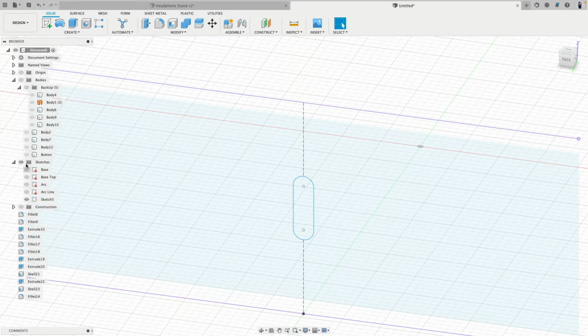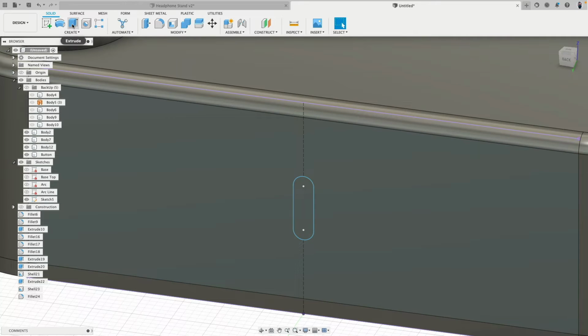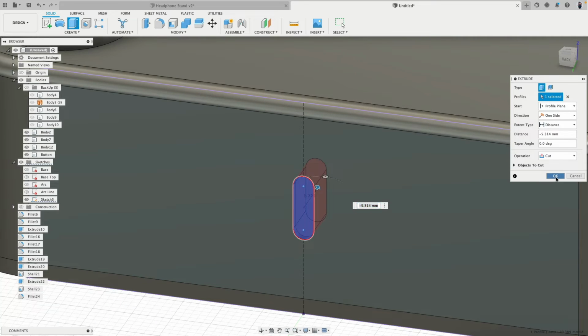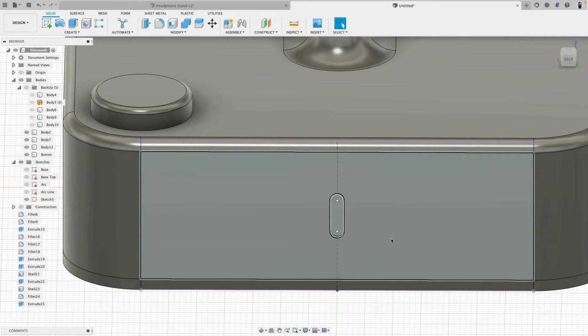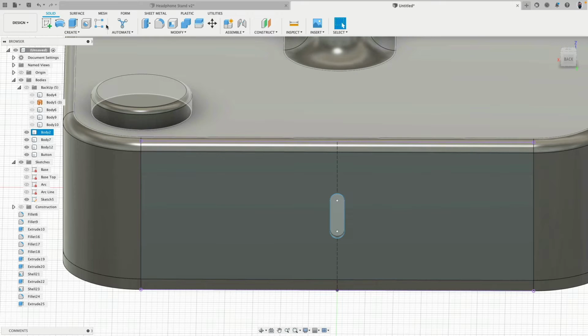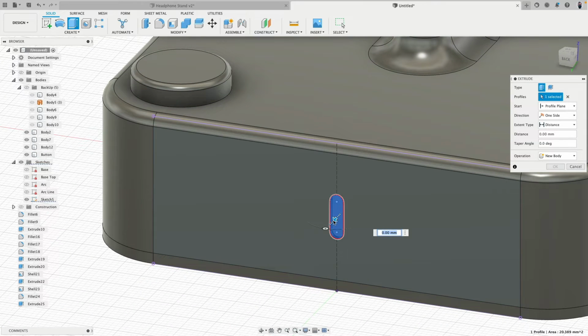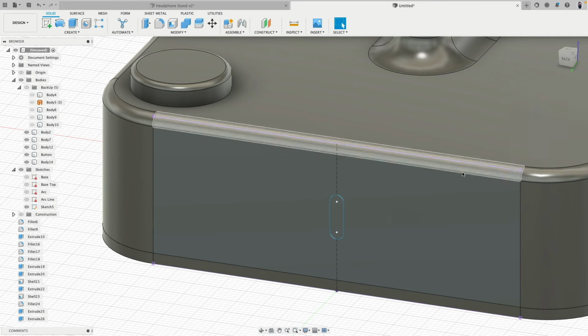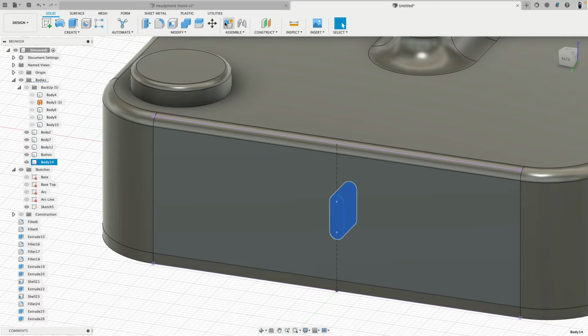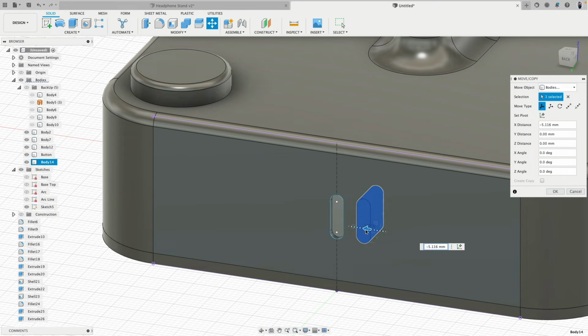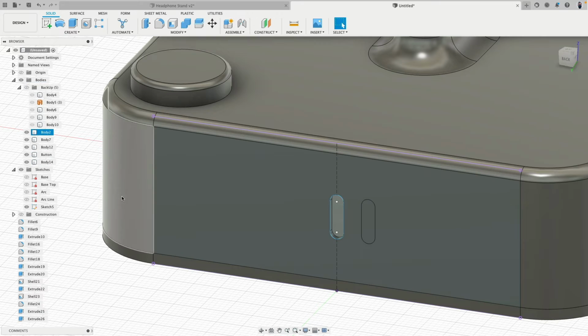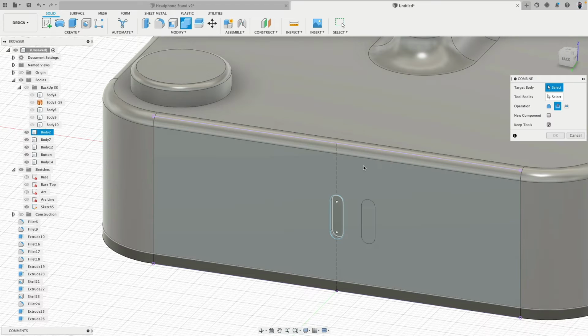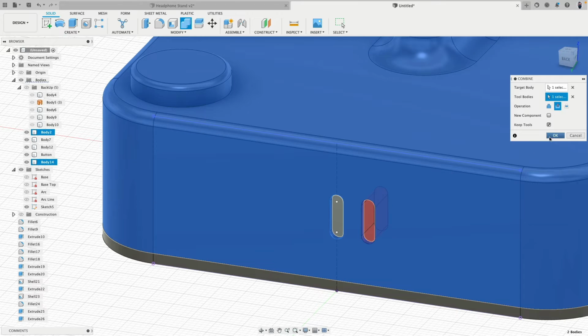Now, let's go back to our body. We have this opening. So now we can cut through. Yeah, there we have an opening. So there are now two ways to continue with more of these cuts. I could select this, make a new extrusion, but as a new body. And then this piece I move over by -6 millimeters, and then remove this one.